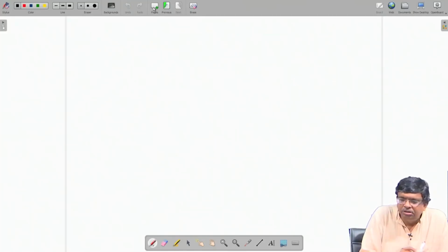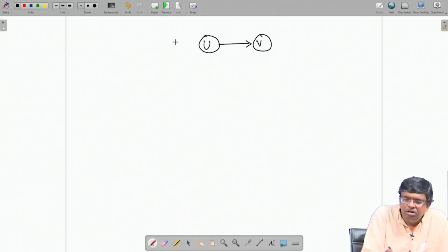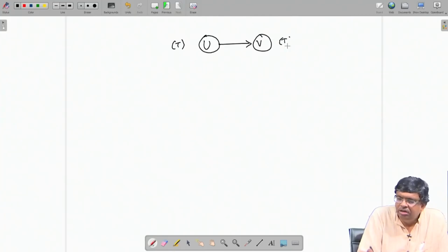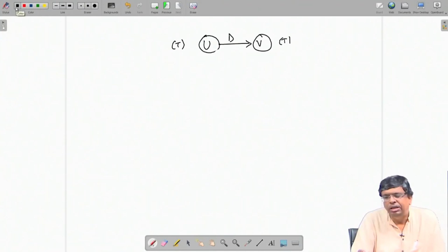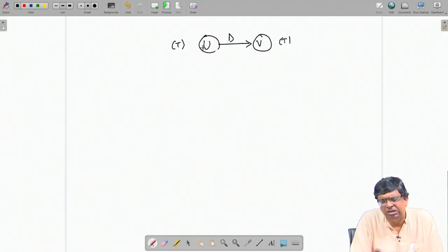I will show you an implication. Suppose I have a process, just U and V, all right. This takes time t, this takes time t. Okay. So, the critical path is t plus t, 2t. I mean, to minimize the critical path, I do a cut-set retiming here, I put a delay, all right. So, now critical path is t, because in one cycle I do the job here, next cycle only that output is required here, it takes a time t to do operation on that, at that time it takes time t to process next data, and like that we have been discussing this again.